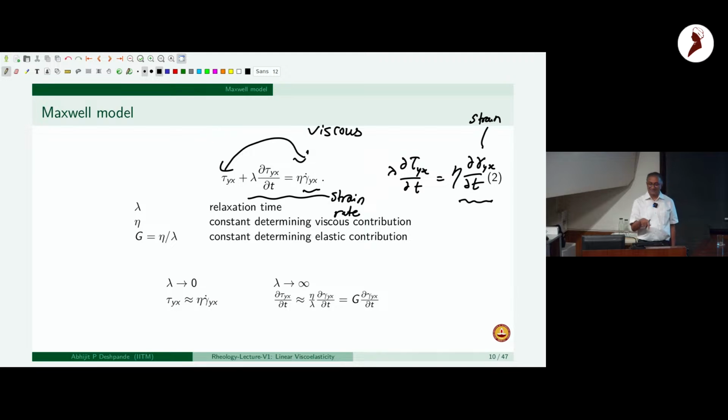Moreover, a partial derivative is not the rate of change of strain. One would have to look at the strain tensor, and its convected rate will give us the strain rate. It so happens that the strain that I defined in the morning and its convected rate is the strain rate tensor that I defined, okay, in terms of the velocity gradient. But this is what one would have to do in general.